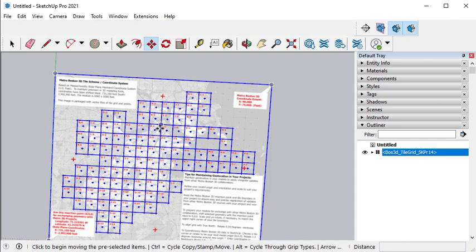And if you try to use our data in this citywide coordinate system, or Metro 3D coordinate system as we call it, you'll notice a lot of choppiness. You'll notice imprecision when you try to draw small objects. They will tend to snap in awkward ways and collapse. Your views will be clipped when you try to render things in perspective. The computer will appear to be confused. And so don't try to use our 3D modeling resources in this coordinate system.